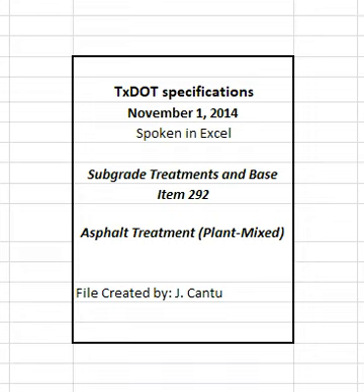When using 3-wheel, tandem, or vibratory rollers, first roll the joint with the adjacent pavement. Continue rolling longitudinally at the sides, proceeding toward the center of the pavement, and overlap successive trips by at least 1 foot unless otherwise directed. Make alternate trips of the roller slightly different in length. Begin rolling of super elevated curves at the low side and proceed toward the high side unless otherwise directed.